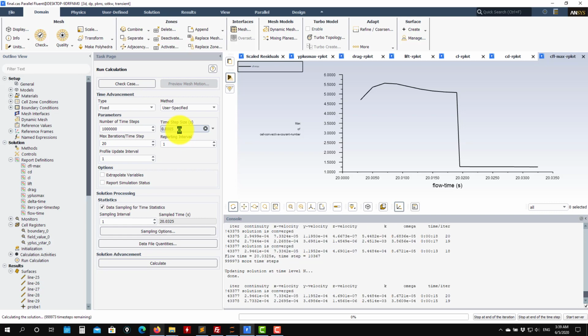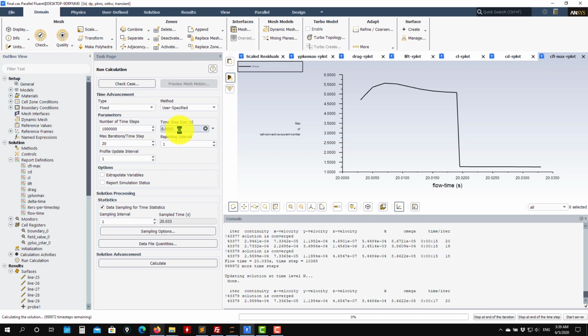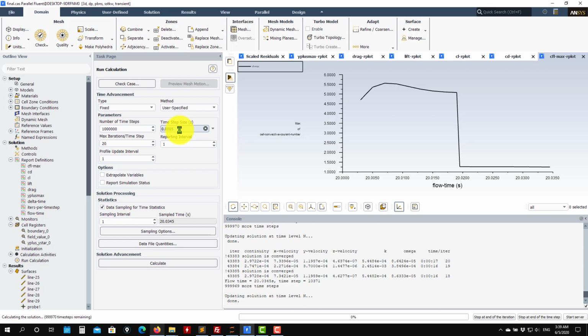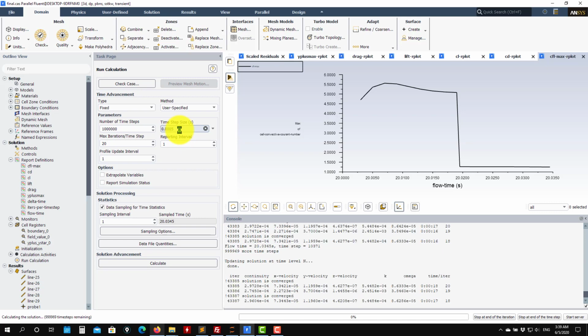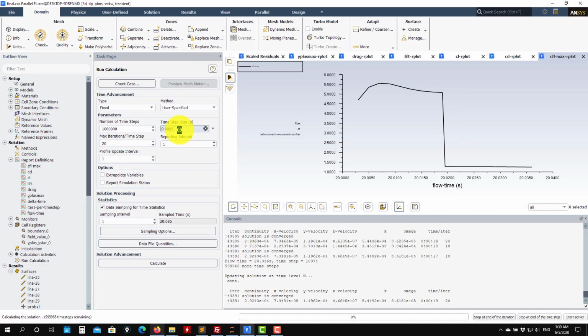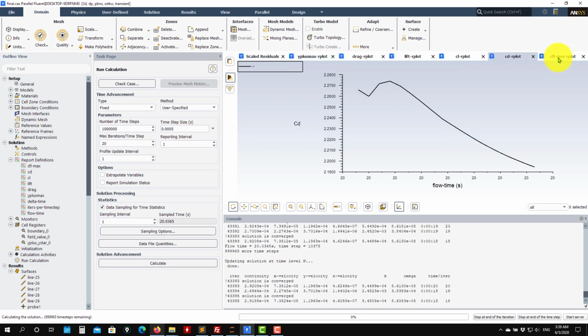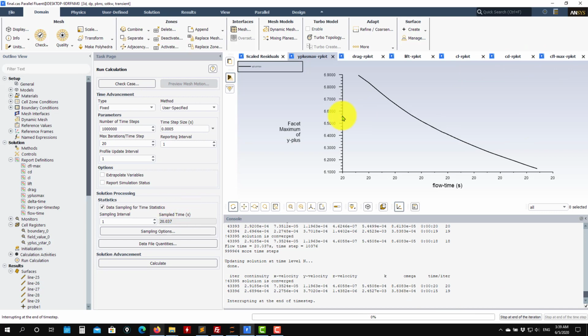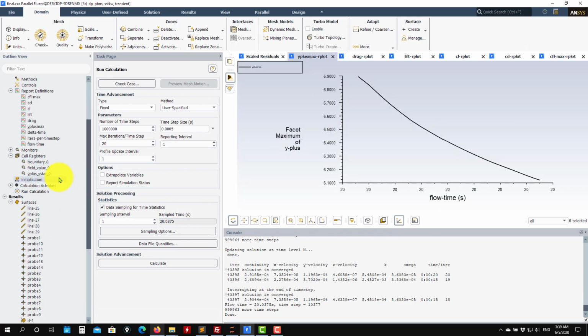Use wall functions on unsteady. On the other side, if you are doing steady simulations, my advice is always go for wall resolving. Then you can interpolate a wall resolving solution into a wall modeling mesh with no problem. We have done that. Okay, so if I stop here, we got the idea.